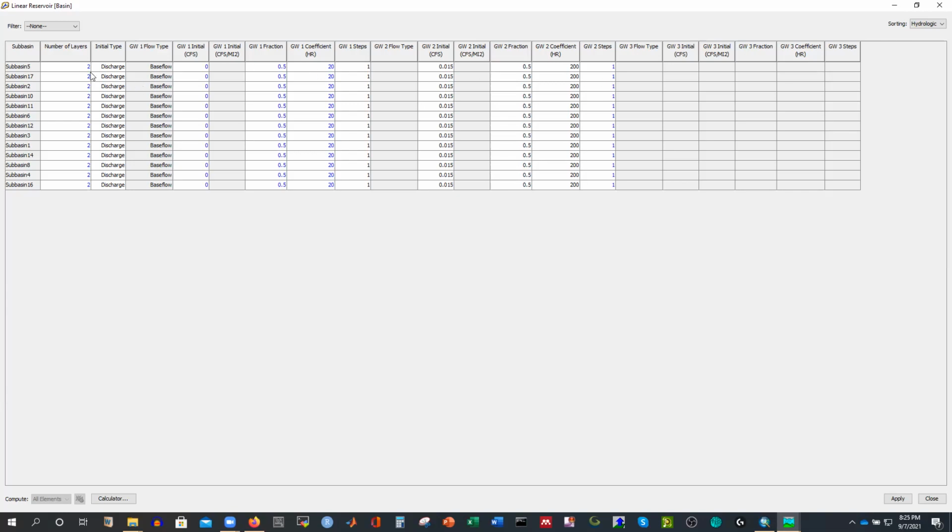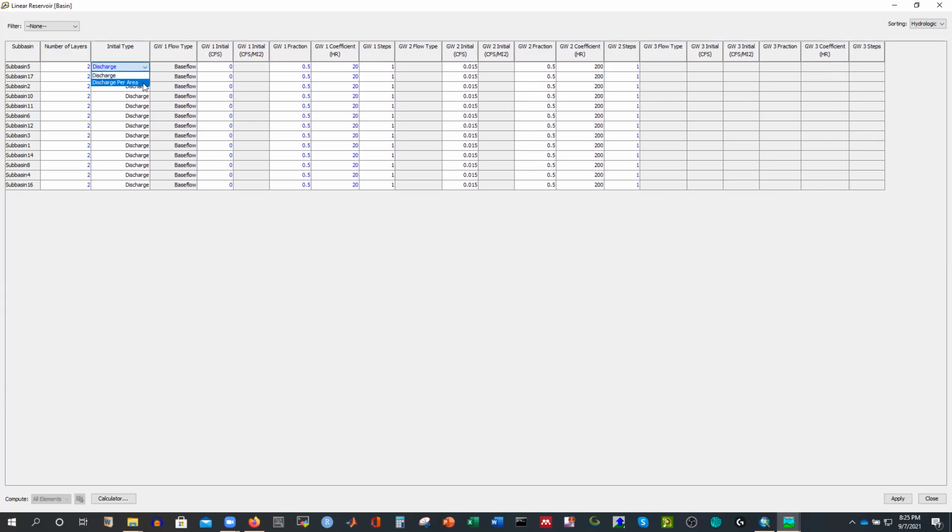So that is the thing where we selected, just let me check it pretty quickly, 2 layers of groundwater, and we are selecting that type, it is flow rate, but we have to select it as flow rate per area. That is the most convenient. Other people use that instead of flow rate. Then it will be easy. These come from experience, okay? People use this from experience, so you can do the same.